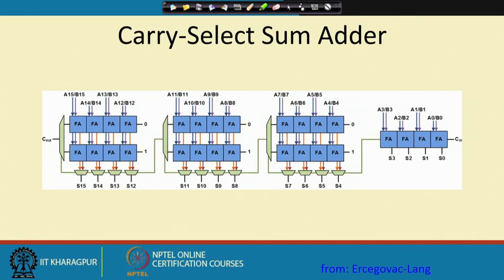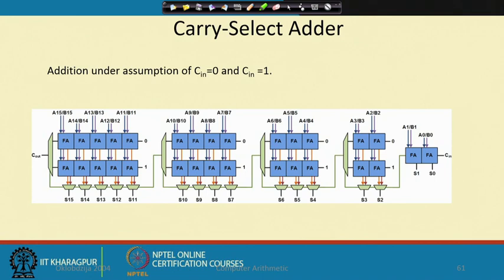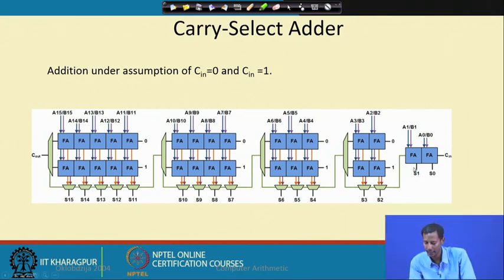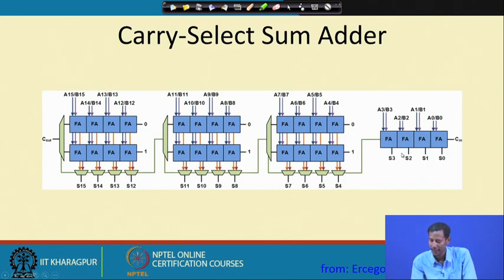In this particular case, can you do something to get a reduction in the critical path? Okay, so here also we can do it. Going back to the previous one, what I said was that for this I need 4 full adder delays, and then a total of 6 multiplexer delays.